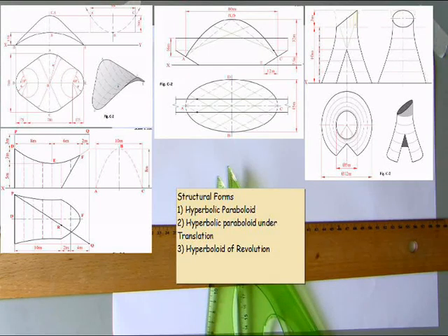There's another variation of it here, where you have your parabola, your ABC parabola, and that is going to travel, point B is going to travel along the curve here, DEF. So it's like it's on a zip wire, or some sort of track, where DEF is the track that it's going to travel, and as it gets lower and lower and lower, the parabola gets shorter and smaller because it's being cut off by the ground, and then that will solve your plan view here.